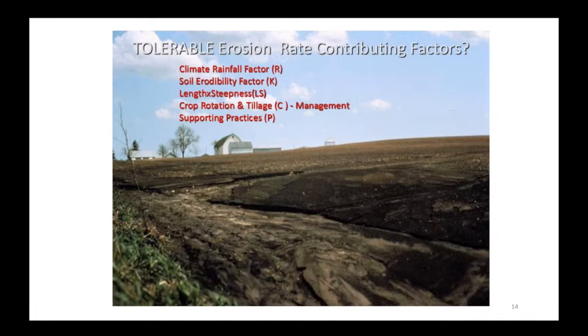And so that's the crop management factor. But keep in mind that within the universal soil loss equation, you as a planner and the producer have control over that C management factor. Also, the supporting practices, and we have a wide range of supporting practices: contour buffer strips. We have what we call contouring, meaning that we are going around the slope perpendicular to water runoff.